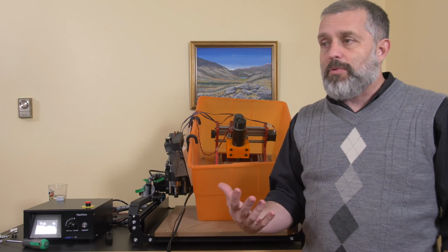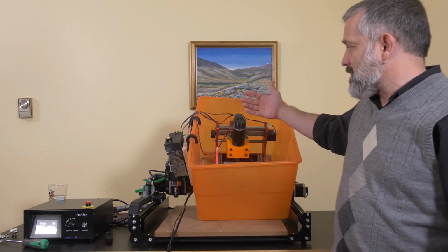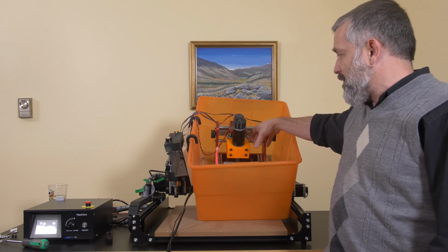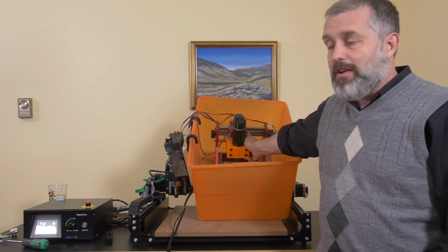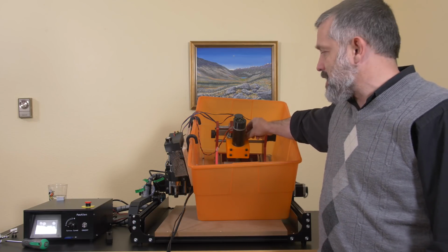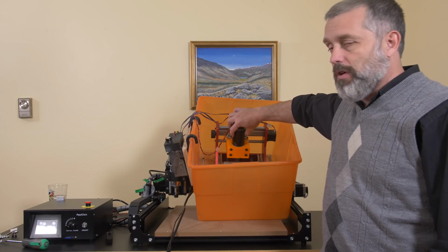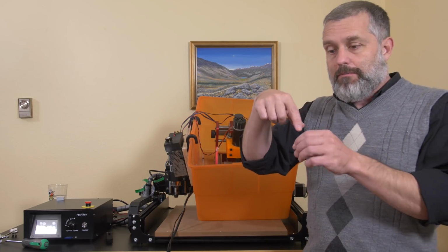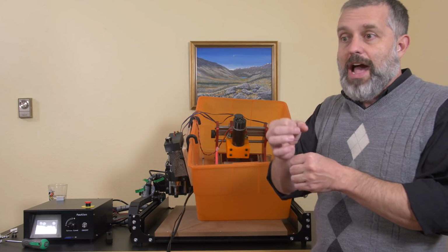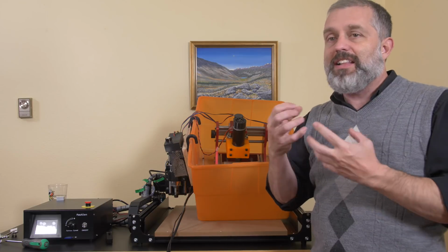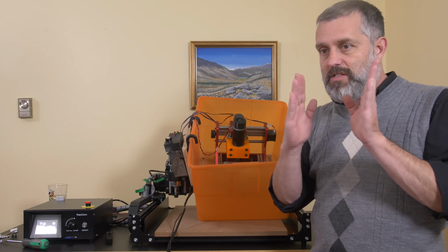And the other reason I'm throwing in the towel is because fundamentally, I don't think I'll ever get this machine to work. Even if I replace those brackets with metal, and there's absolutely zero flex between the bearing blocks and the motor because it's metal, I still have bearing blocks on 12mm shafts. Well, those aren't perfect. It's not an interference fit. They slide, so there's a slight wiggle.